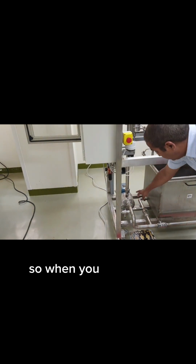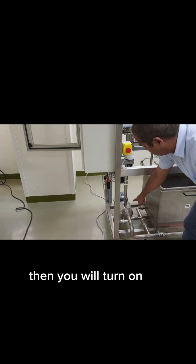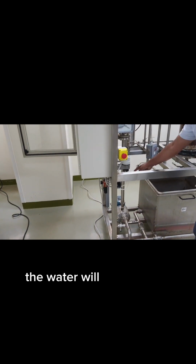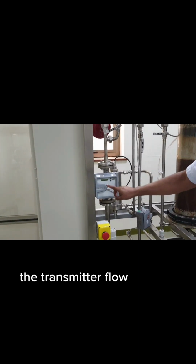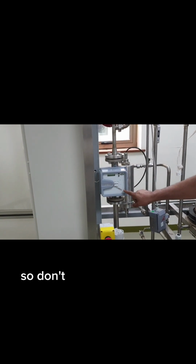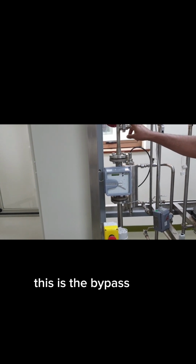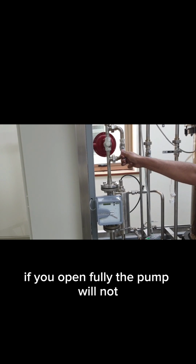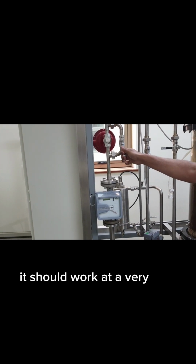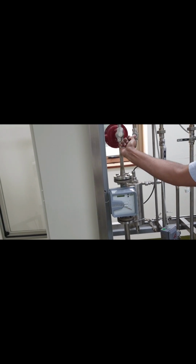So when you turn on pump G1 from the panel, the water will go out through the flow meter. This is the flow transmitter, it transmits the flow, and it's called the flow meter. Don't put it at more than 500. This is the bypass valve. It should always be like this. If you open it fully, the pump will work at a very high rate. So in order to control it, you have to keep it partially open. Partially, yes.